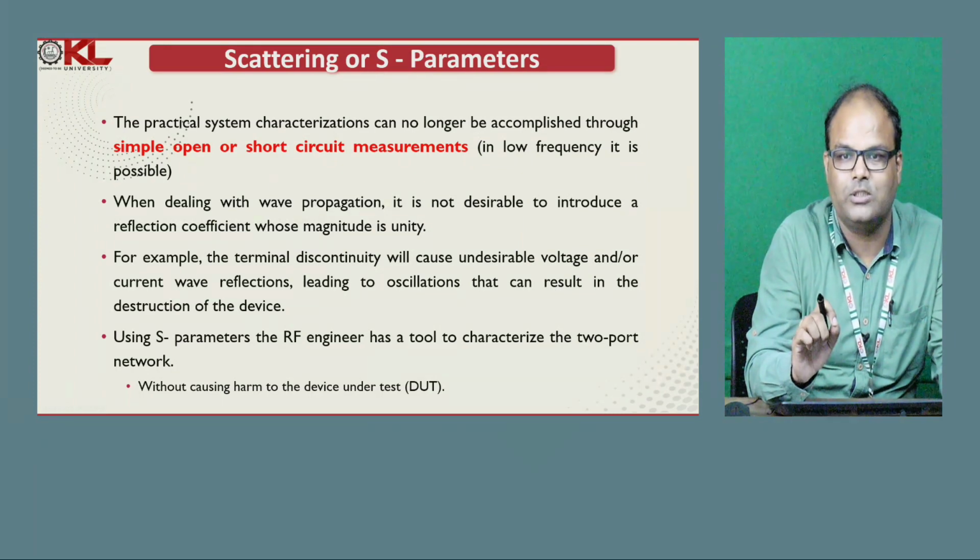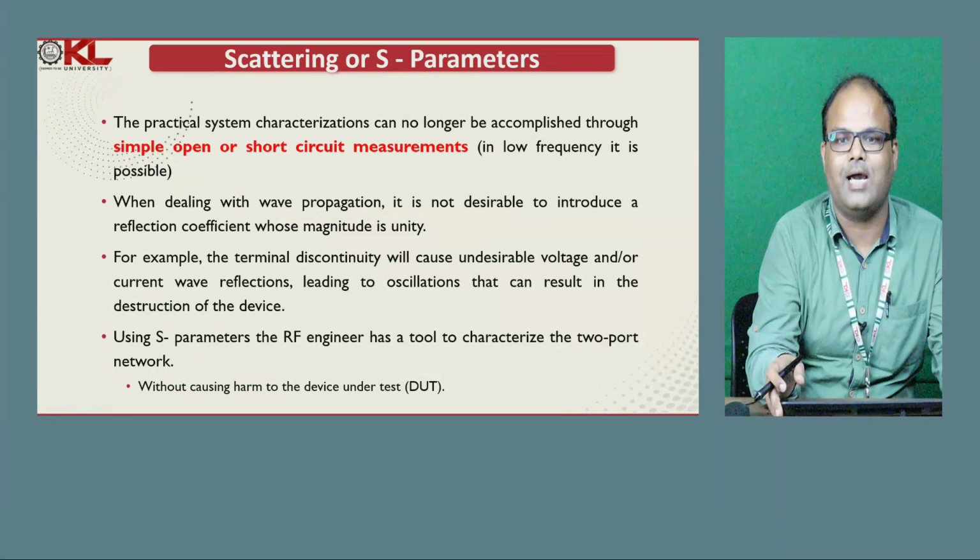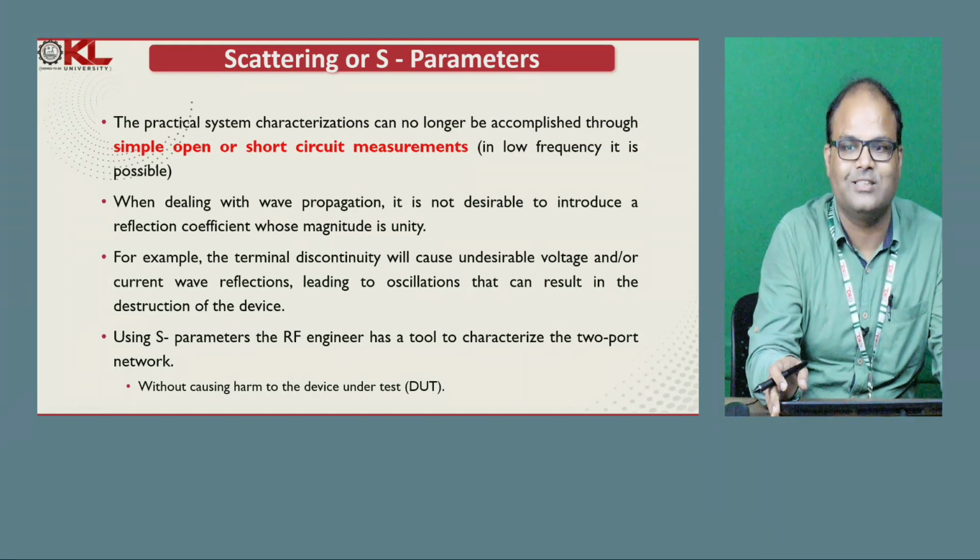For example, a terminal discontinuity will cause undesirable voltage and or current wave reflections, leading to oscillation that can result in destruction of the device. Using S parameters, the RF engineer has a tool to characterize the two-port network without causing harm to the device under test.